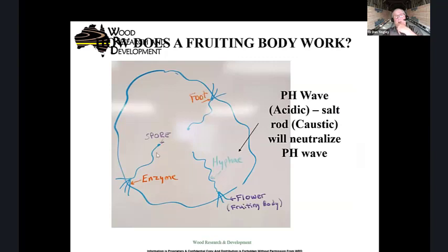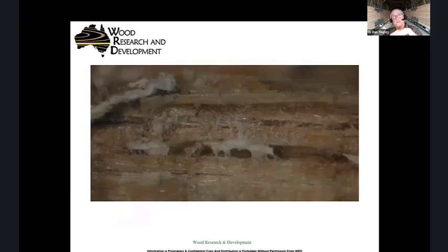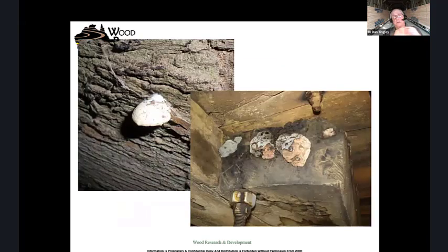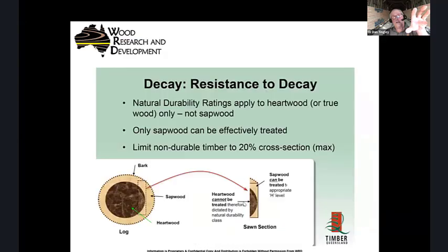So if I take a spore, it grows a hyphae. It has a foot on the end of it, secretes an enzyme. The enzyme breaks the wood down. It's a cycle of life. We just don't like that cycle in our timber bridges. So we have to do things as engineers and designers to prevent this fungal colony from attacking our timber. This is a treated ironbark piece from Victoria with a bolt in it, 8 years old, and here are fungal fruiting bodies growing from it because we've chosen verticals to come from the top inside the decay zone.